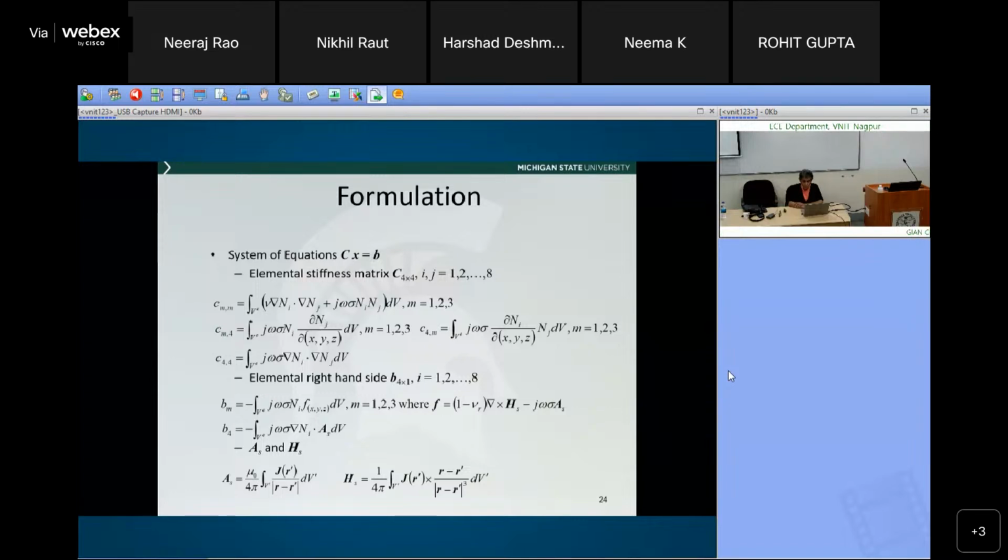So what I need to do is compute AS. I can use the mesh, any arbitrary coil geometry, which I'll show some of these in the afternoon, and you numerically integrate, evaluate this integral. So that means the source field is known. I don't have to mesh it. Once I've done it, I have the field calculation. I just use the field, wherever the coil is going to be.